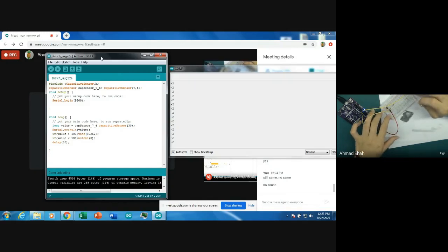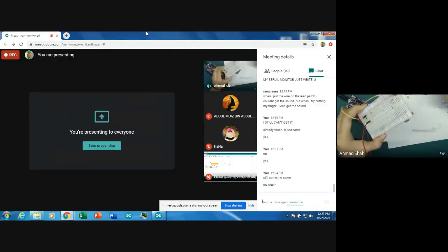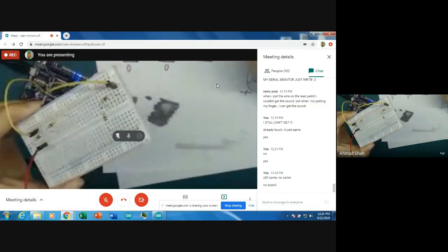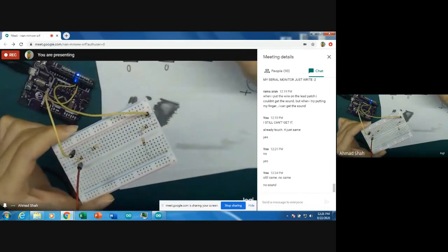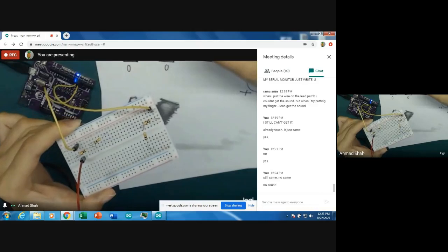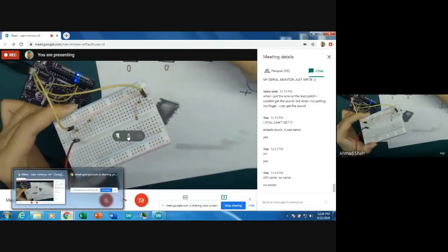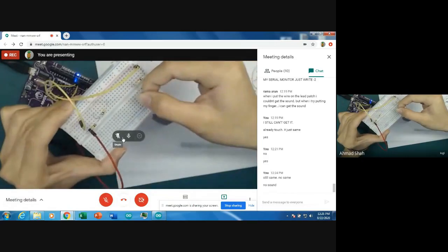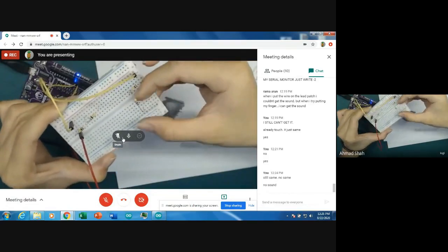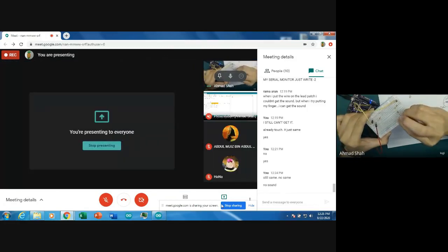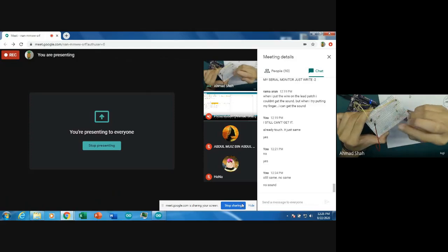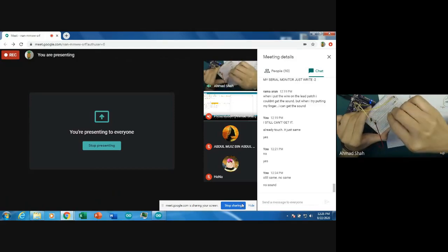Oh, there I get -2. So this is how I get -2 when it's like this. But I don't know why. So probably one of your resistors is not really connected properly. So now try to press a bit inside, make sure your resistors are totally in. I think you did not connect the resistor properly.